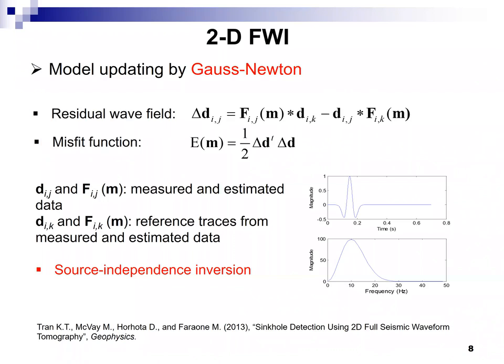So we can use any source signature for wave simulation, to answer the question. We can use a Ricker wavelet, a sinc function, or even a triangle wavelet to simulate the waveform. And then we do the convolution like this. We don't need to know the actual force applied into the ground, because we don't measure it using the sledgehammer. For example, we can use a Ricker wavelet like this, with unit magnitude and any delay time. The only requirement is that the frequency content of the source signature is similar to the frequency content of the analyzed data. For instance, if we do 10 Hertz analysis, we need to put the central frequency of the source signature at 10 Hertz.